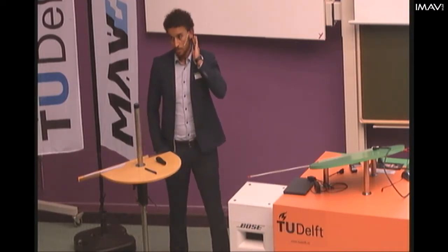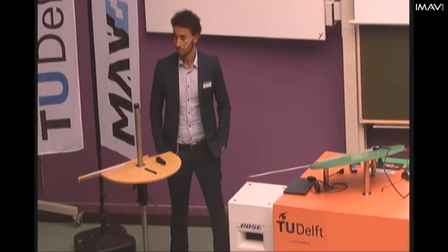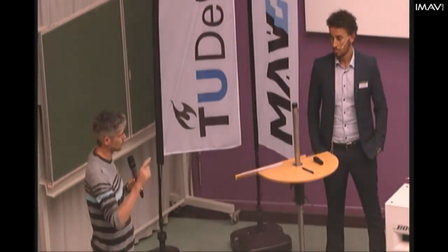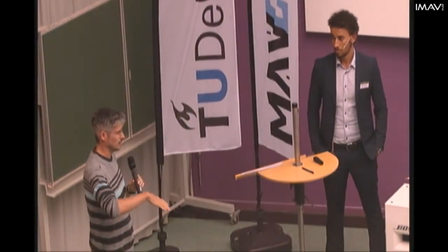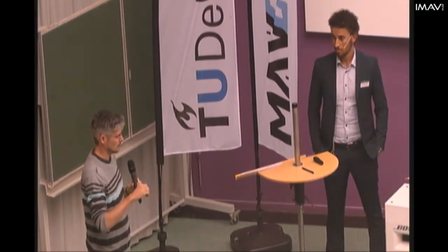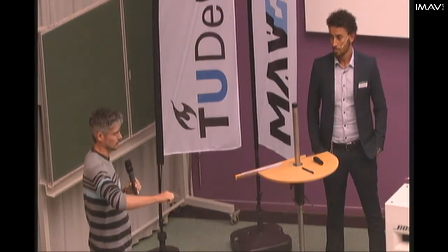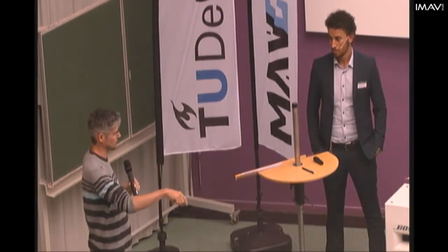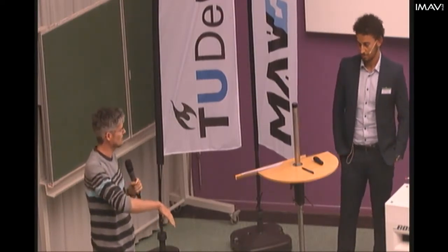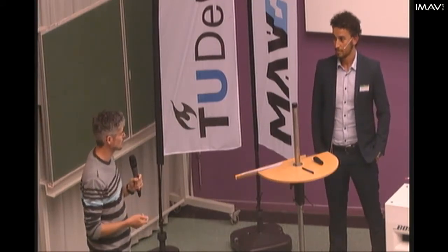When you fly a quadrotor going forward, gaining some speed, what you see when you pilot manually, or if you look at the integral part of your control, is a kind of pitch-up effect. It means that when you keep going banked, your front propeller will finally turn much slower than the one at the back, because you have to push the back propeller to stay banked. Did you try to measure this effect?